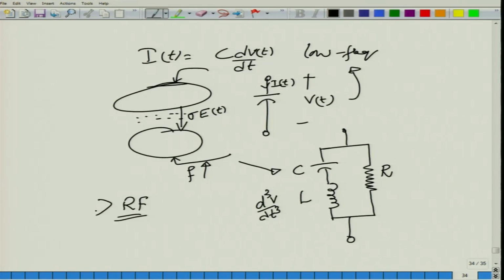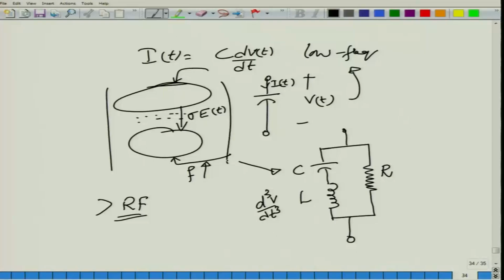So at millimeter wave frequencies or other places, the capacitor that we think of as a very ideal element will no longer be an ideal element just relating I, C and V, but will also have to be modeled as a capacitor, inductor and a resistor. I hope you have come away with a very important fact, that the physical scenario is different from the mathematical approximation.